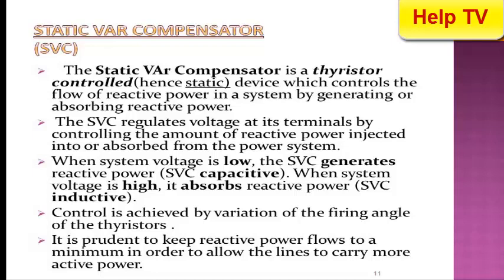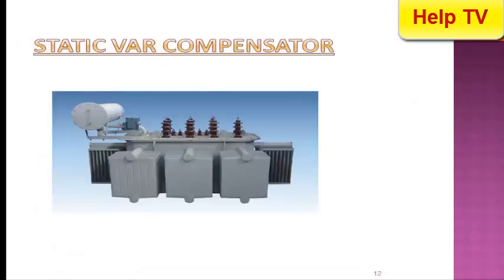Control is achieved by a variation of the firing angle of the thyristors. It is prudent to keep reactive power flows to a minimum in order to allow the lines to carry more active power.